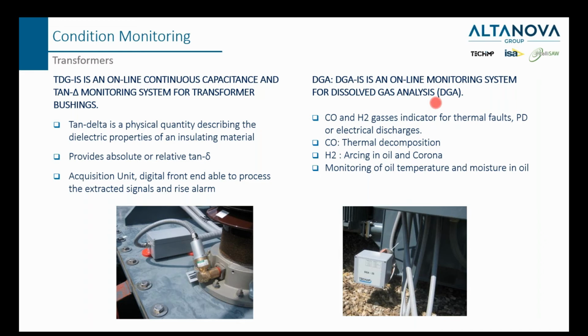All the monitoring solutions are highly customized. So the two-gas DGA analysis is our typical offering. I know some customers prefer to have more advanced DGA analysis, which is fine. We can easily change our DGA unit to a 7, 8, or 9 gas analysis component. So as I said, all of those are very flexible and can be customized.